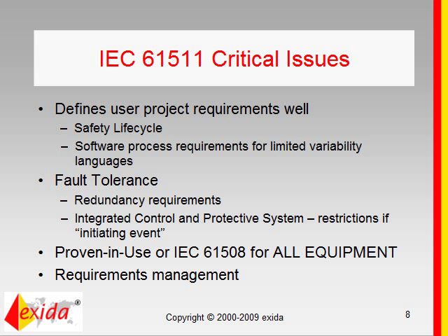It also addresses fault tolerance and redundancy requirements. It does talk about integrating control and safety. There are some restrictions if the control system is the initiating event. It talks about prior use or 61508 compliance for all equipment. And then finally, it requires the management of the requirements within a project.